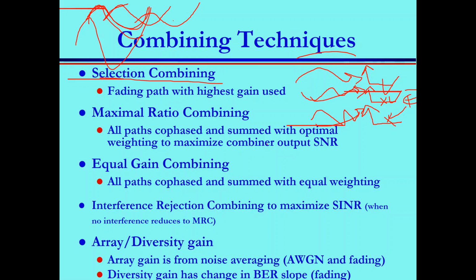Because phase is important. If they are not aligned, if they don't have the same phase, they can add destructively. Their addition does not give you the maximal output. But if you make them all in the same phase, when you draw them in the two-dimensional diagram, this is in the same phase. This is the amplitude of the first channel, this is the amplitude of the second channel, and this is the amplitude of the third channel. When I tell you to find the resultant in physics, what do you get? You get a line of this length.